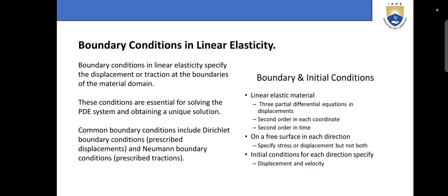Boundary conditions in linear elasticity specify the displacements or tractions on the boundaries of the material domain. These conditions are essential for solving the PDE system and obtaining a unique solution. Common boundary conditions include the Dirichlet boundary condition, which specifies displacements.